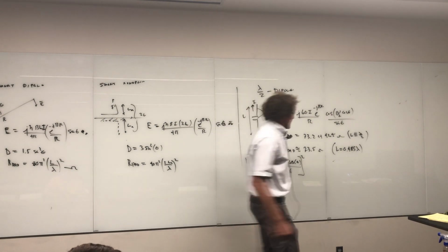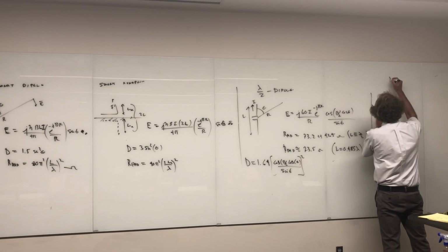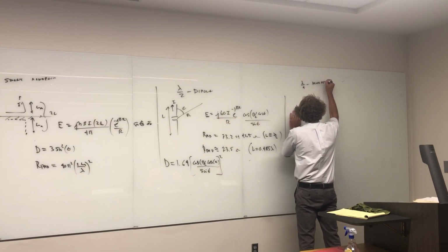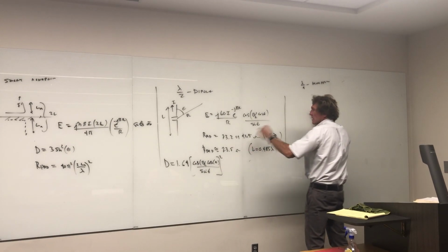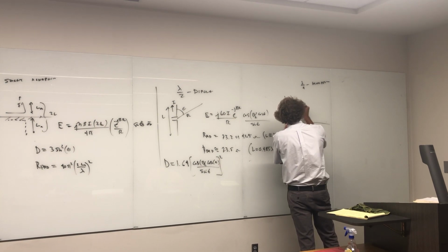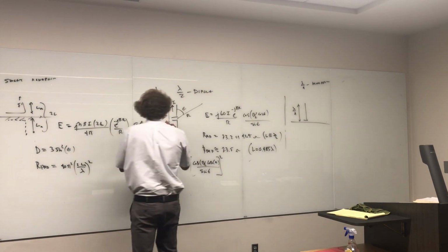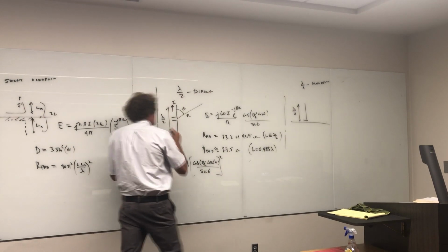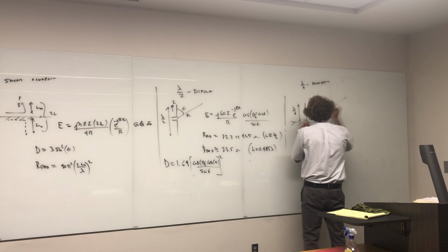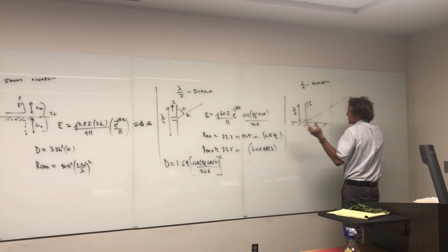Okay? Next, when we do the dipole, or the quarter wave lambda over 4 monopole, you just have an antenna like this, where now this is going to be lambda over 4. Before, this L right here was lambda over 2. If that's lambda over 4, and this is the ground plane, coming out, if this is a current I, electric fields are going to be the same. Actually, they're identical.